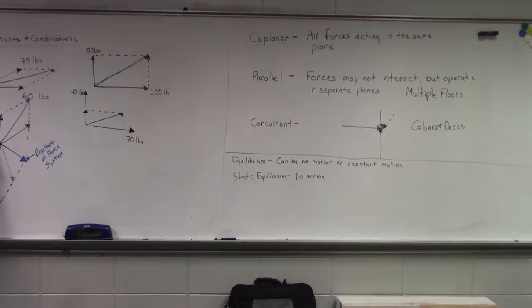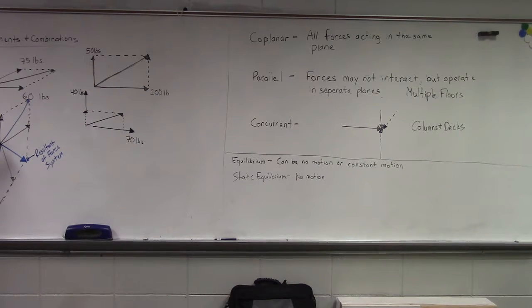I don't want to have a connection resisting this force, on and on and on. If I can determine the impact of all these forces and get them into one force, I can say, Mr. Contractor, you need one connection able to resist X load, 400 pounds, at this angle, okay?